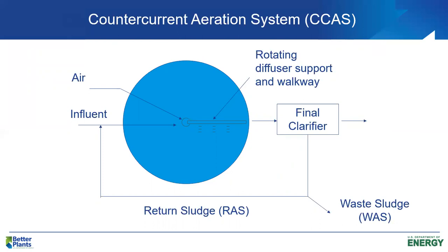And as it moves around the ditch, then right behind where the aeration equipment is, we'll have fairly high dissolved oxygen, maybe 1 to 2 to 3 milligrams per liter. And as you get further and further behind the rotating arm, then the DO may actually go near zero, so that with this process, you may actually be able to also nitrify and denitrify within the biological reactor.